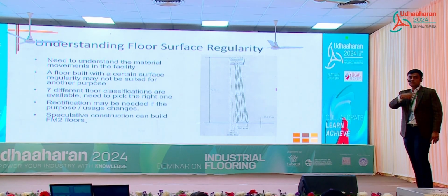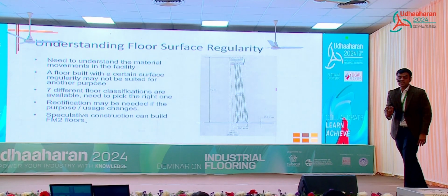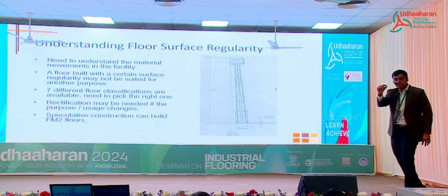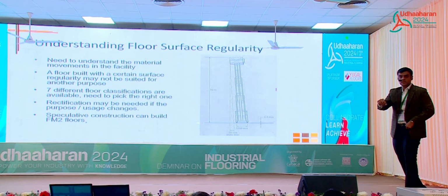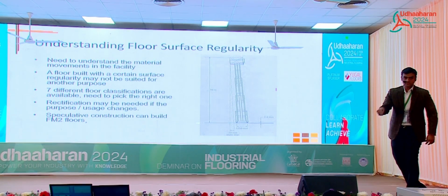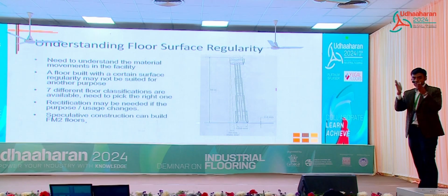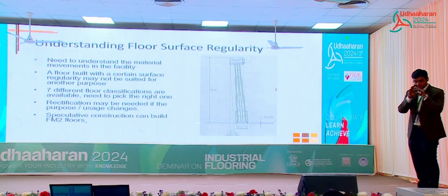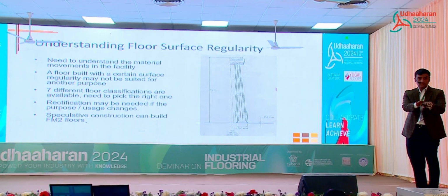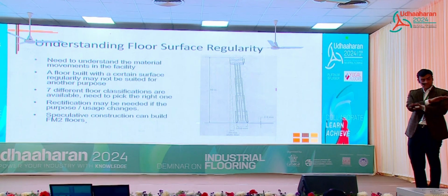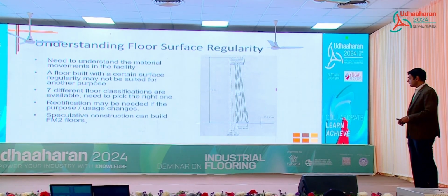Flatness is not related to seeing how much water is standing on your floor. You should not be taking a coin and harassing us, saying this 5 rupee coin or a 2 rupee coin is getting submerged, as long as your survey is passing, as long as you're within the limits. If you've defined your flatness properly based on your functional usage, you will be fine.